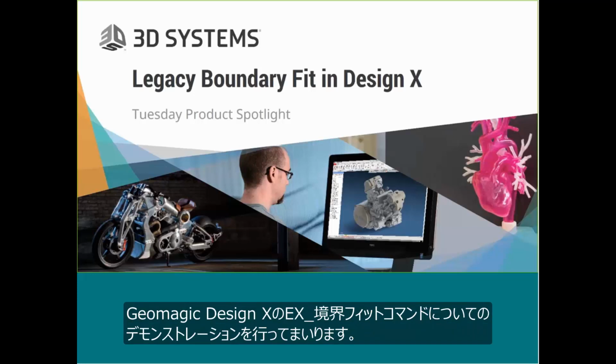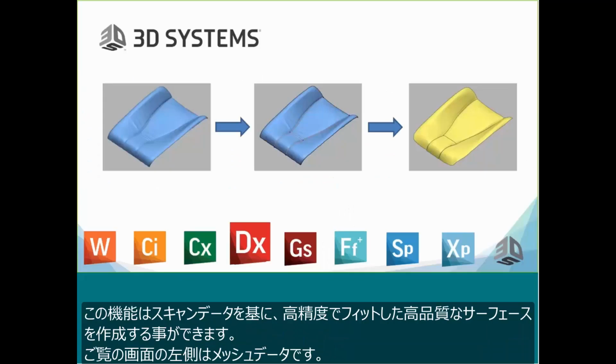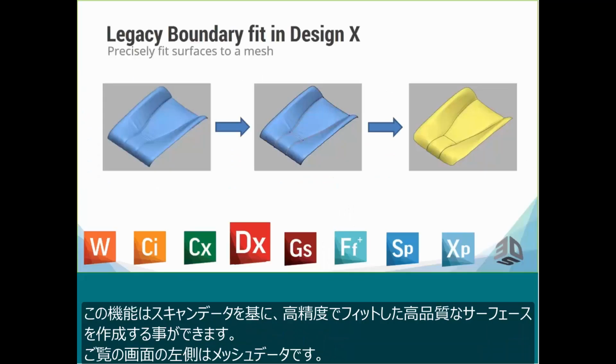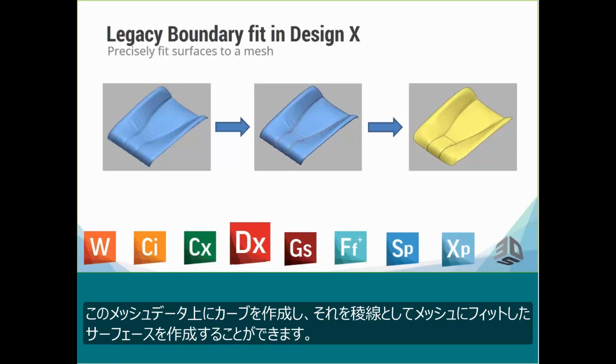I will be going over a demonstration of the Legacy Boundary Fit tool in Design X. What that does basically is allow you to fit very accurate and precise surfaces to a mesh. There on the left, you'll see a picture of just a plain mesh. In the center, some curves that we've been able to place on our mesh, and then using those curves, we fit surfaces using the curves as a boundary.